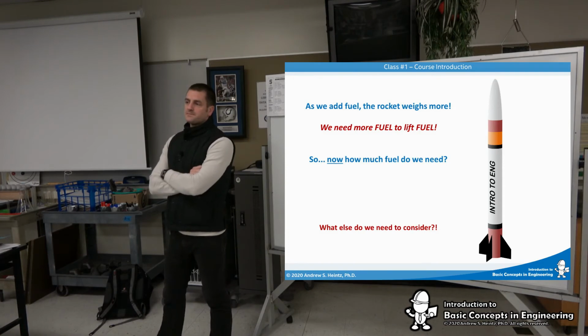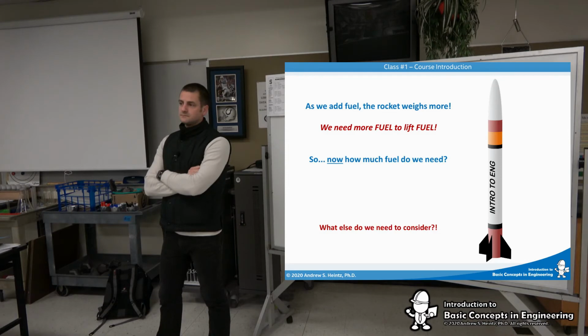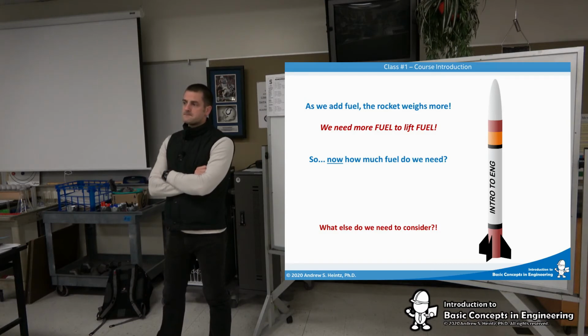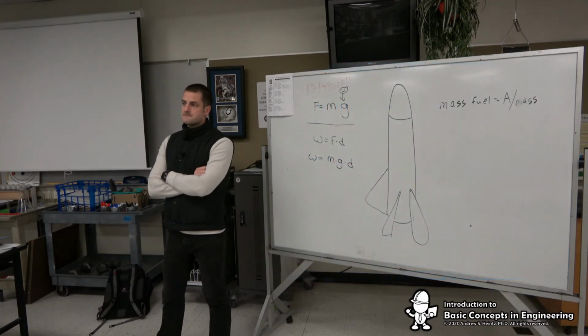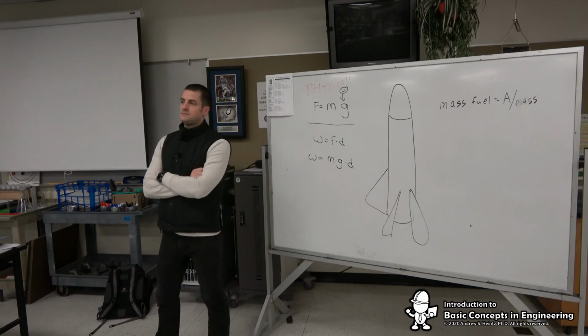And you're going to need the caloric density of the fuel, or how much energy it's going to release when you burn 1 kilogram. And also, if you're talking from a cost standpoint, if you're going to use a less efficient fuel, you're going to need bigger fuel tanks, depending on the density of fuel. So you kind of have to optimize that as well.